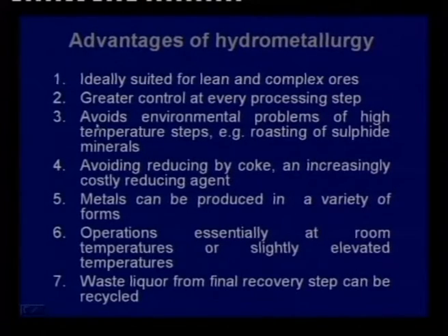We came to hydrometallurgy, saw the advantages, and I mentioned it is ideally suited for lean and complex ores. There is greater control because things are happening at low temperatures, room temperatures very often, or slightly elevated temperatures, and it is easy to control because things are not happening far too rapidly. Environmental problems coming out of gaseous emissions are not there. We do not have to depend on coke as pyrometallurgical operations very often depend on. It is becoming a costly reducing agent. There is no question of CO2 emission.